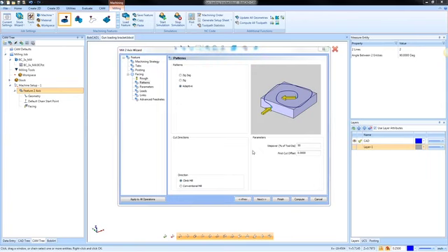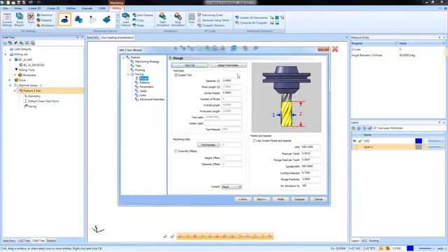All right. Let me see here. John, is it recommended workflow to type in the tool data on the fly or set up tools in the tool crib? Thomas, I do recommend, here I'm just typing it in on the fly, and what it will do is if this tool size lives in your tool library, then it will call that tool. I do recommend that you set up a tool crib and you load a tool crib at the beginning of a job. I think that is very helpful, but it really just depends on your shop and what kind of equipment that you're using. So it could work either way, but I do generally recommend setting up a tool crib and loading a tool crib before you start programming.